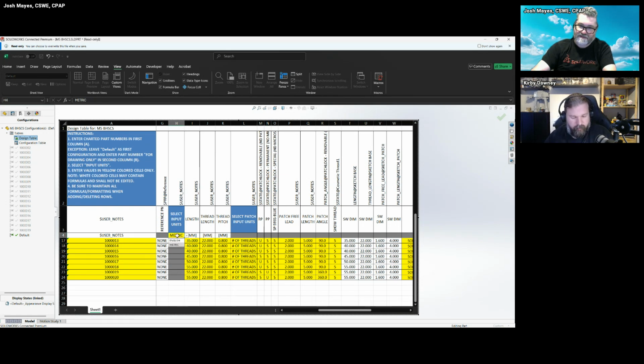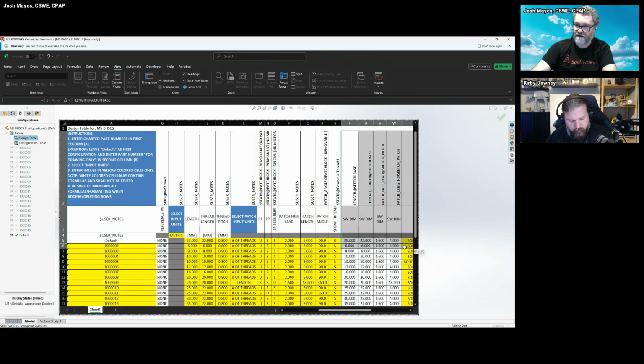So you can see what happens if I switch this input value, and notice this is the first time we see the user notes as a column. So I'm using this column and the next 4 columns, none of these are driving anything. They're just giving me the ability to specify things in Excel that drive the actual fields, which are over here, these SOLIDWORKS dimension fields.